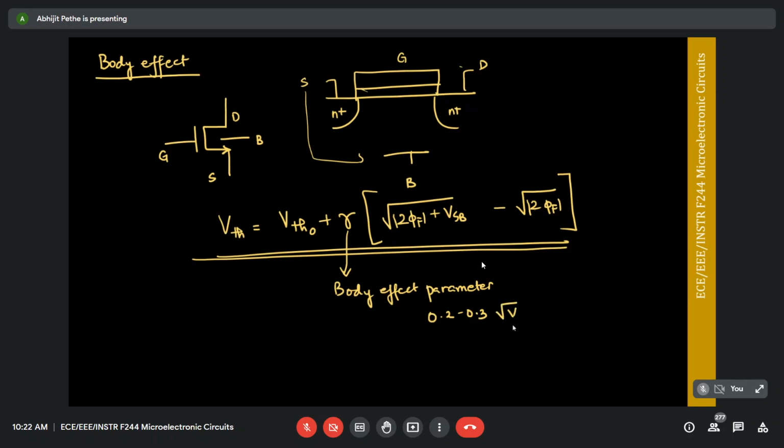Again, we will not obsess ourselves too much in this class because we're doing the first class in analog design. But when we do advanced analog design, we will come back to this. In most cases, we will either ignore the body effect, assuming gamma is equal to 0, or we'll always assume that the body, substrate and source are tied together. So in this class, you don't have to worry about the effect of gamma. But remember, in reality, gamma is a real effect.